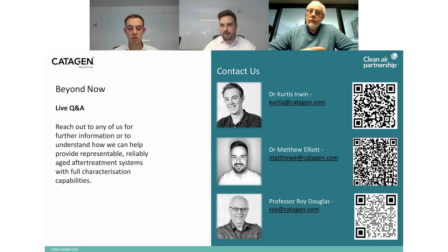So I think it effectively allows a much more tangible metric whenever we're thinking about emissions compliance to be determined during the aging process, for example, or during PGM optimization type activities and so forth. And so I think that's where a lot of the additional benefit over light off and OSC is. Now they're still critical parameters for catalyst development and quantifying catalyst behavior, but for transferring that into what we might expect vehicle behavior to be, I think that's really where the drive cycle testing is very useful and important.